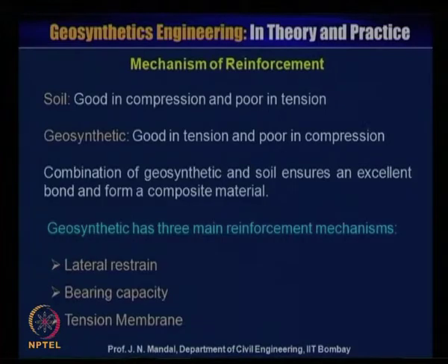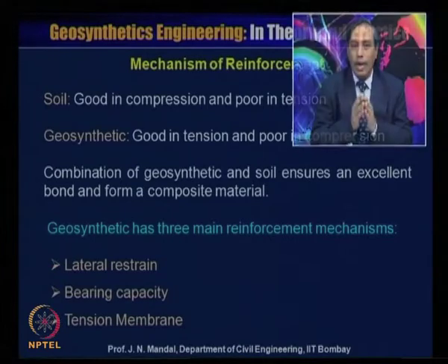Now, the mechanism of reinforcement. As you know, soil is good in compression and poor in tension. Geosynthetic is good in tension but poor in compression. So the combination of geosynthetics and soil ensures an excellent bond and forms a composite material.